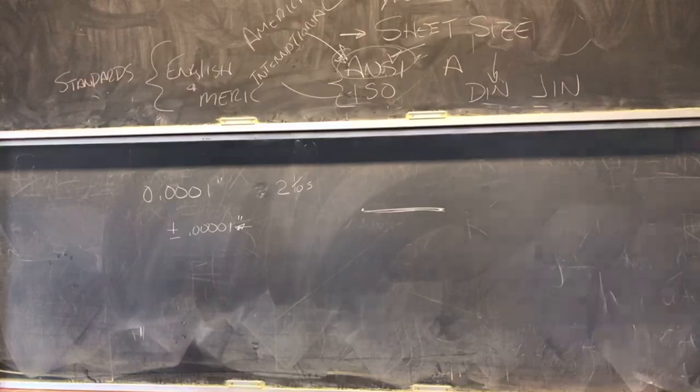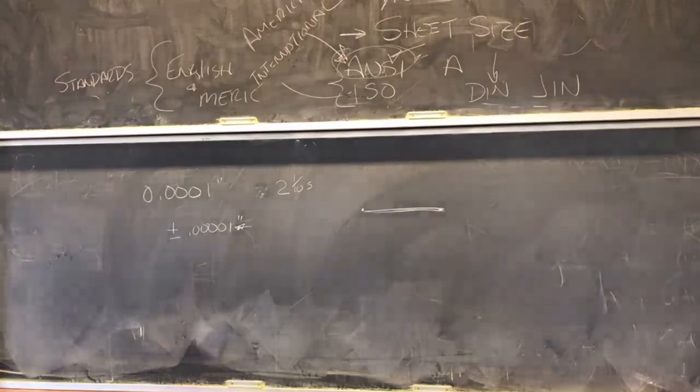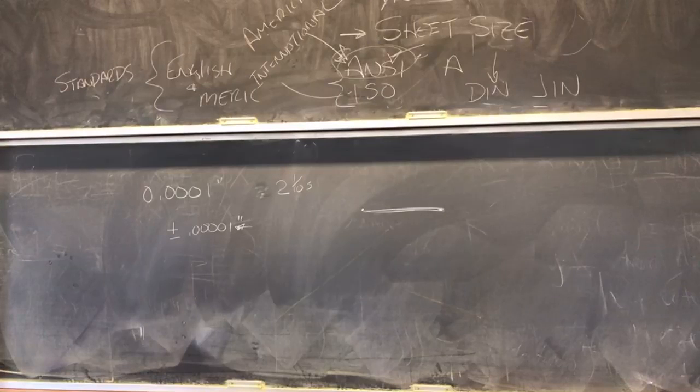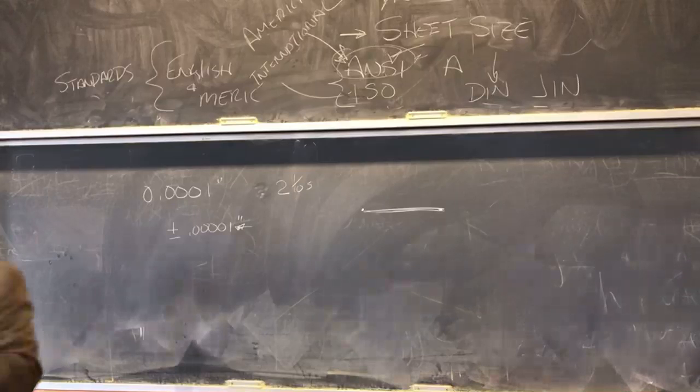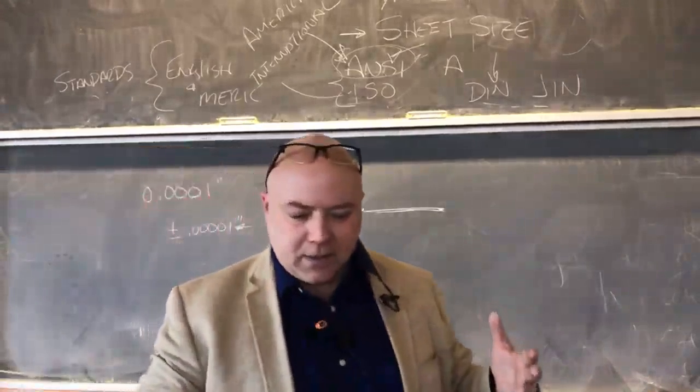We can ignore that a little bit. So we want to calculate how much force it is before we do it. So yeah, it's going to depend on the elastic modulus, the stress and strain of the two materials, right? And the differences in size. So it's going to depend on how much bigger the shaft is than the hole, and what the elastic modulus of the two things are, and then the friction coefficient between them, because you got a normal force coming from the hole trying to squeeze, right? And so it's going to depend on those things.